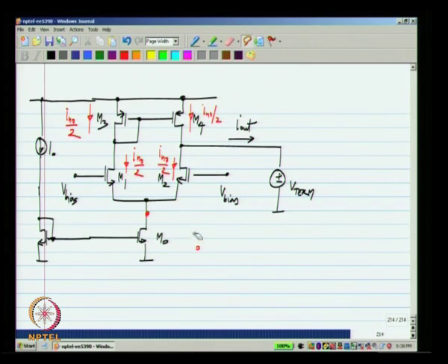We then have to calculate the effect of noise currents in M1 and M2. Let us say I consider the noise current in M1. Okay. Now, the earlier noise sources had one of their terminals grounded. Now, this is connected between two nodes, the drain and source of M1. The analysis can be a little more complicated. It is not very difficult, but it can be a little more cumbersome, but there is a very neat trick that makes it very easy.